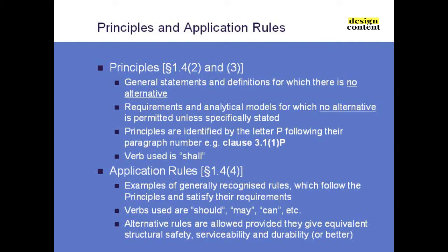So if there's an application rule, what I suggest is you either use it, or if you don't like the application rule, you want to do something more sophisticated, use a more sophisticated computer model that complies with another application rule. So if you don't like the rules, for example, on columns, for buckling of columns and the extra moments, then don't make up your own rule, do a nonlinear analysis instead, which is covered by the Eurocodes.